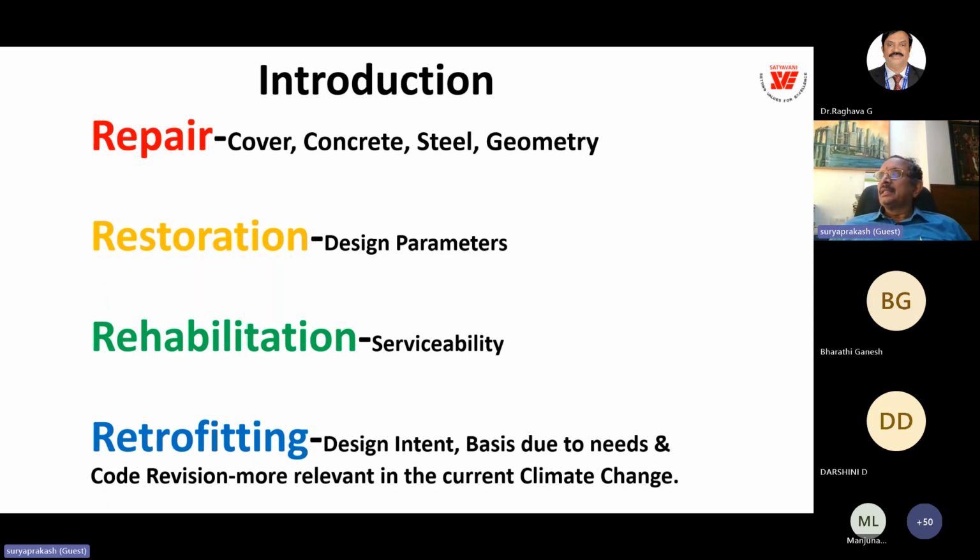condition. Next is the restoration of the design parameters. All the design parameters, whether it is the percentage of steel, concrete strength, or concrete porosity and durability parameters, including the reinforcement, we have to restore so that the structure will perform as per the design for its design life period actually.